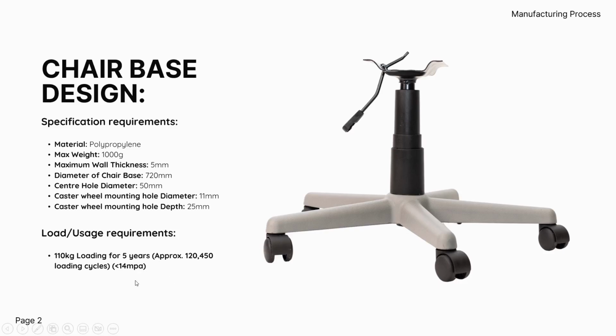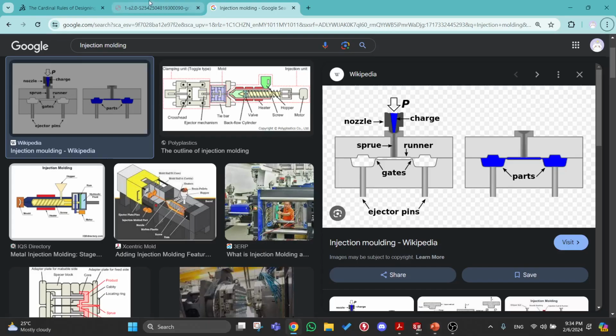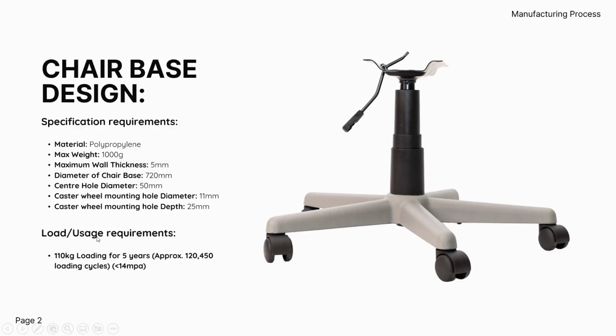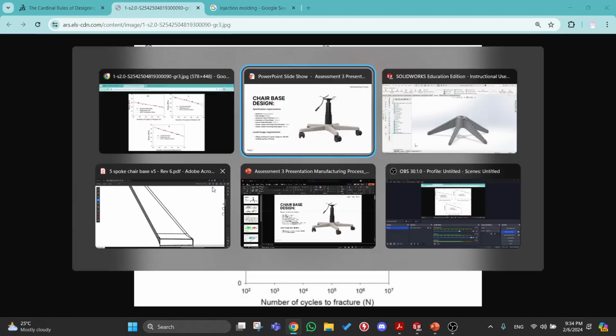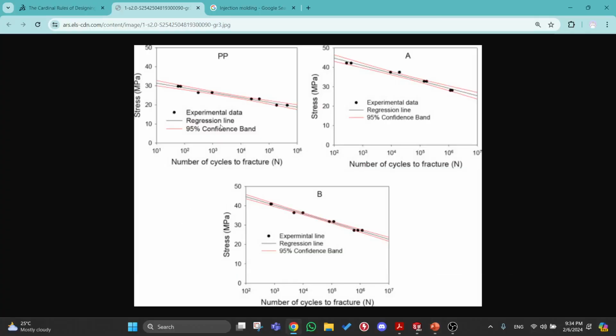Megapascal. This value is gotten through an SN curve, which each material, polymer, polypropylene, has. An SN curve is basically a graph of stress to number of cycles, that shows that depending on the amount of cycles you have, the stress you will need to be able to tolerate.